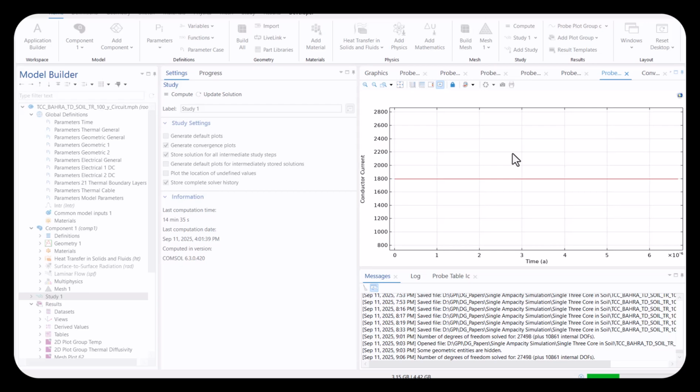Besides transient ampacity, I also have a model for cyclic loading, where a motor or an industrial process is operating cyclically, or electromagnetic propulsion, where again a large amount of current is being fed by cables from a substation or some electrical room, feeding a system where the current drawn is a large amount for a short duration.